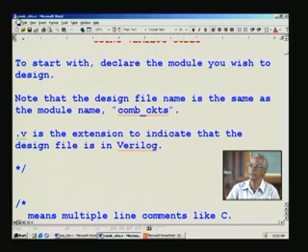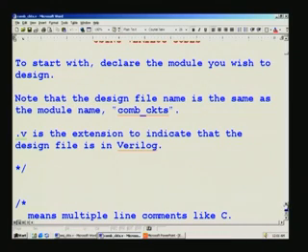And once again I repeat that com_circuits is nothing other than your module name, and the file name should match with that. You cannot nest multiple modules. In fact, I mentioned this in an earlier lecture also. If you have different modules, you have to put them in different files, and call those modules here, and what we refer to as an instantiation. So, we will go into depths of those later on. When the design gets more and more complicated, you have to resort to such methods.